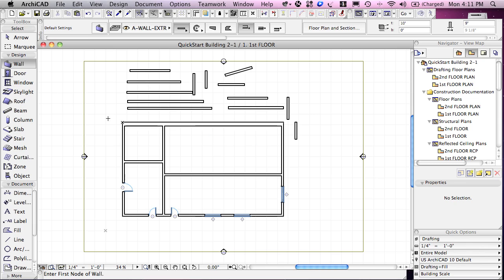So when should you use this? Well, this is a little bit more sophisticated, so perhaps a little early to introduce it, but basically there are times when you want to be able to measure relative to other parts of the project rather than just the last click point, and by using a user origin you can move that wherever you need.